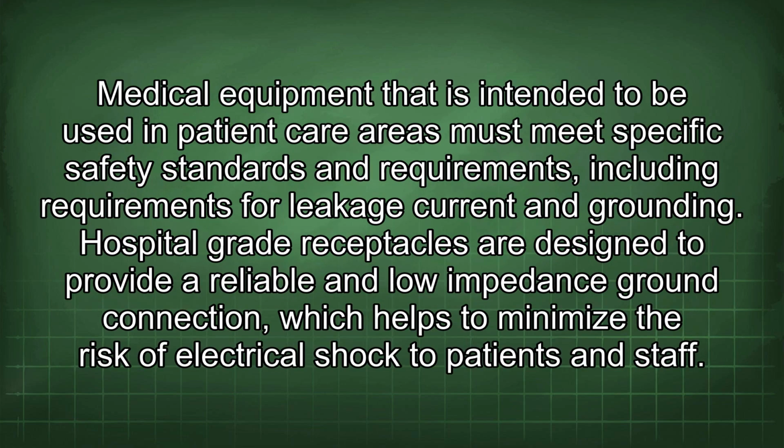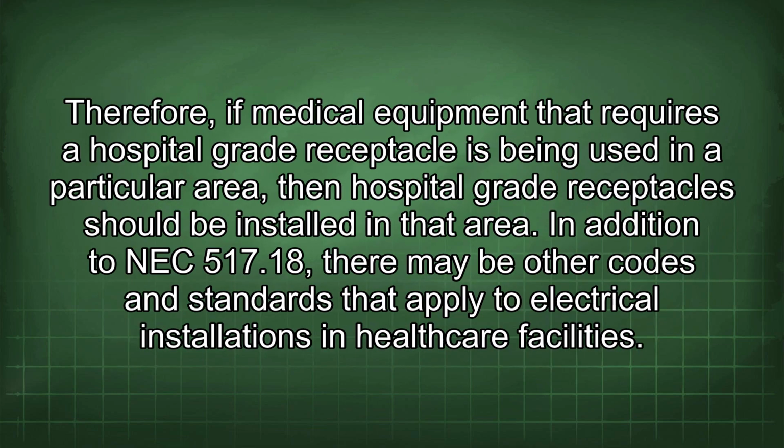Medical equipment that is intended to be used in patient care areas must meet specific safety standards and requirements, including requirements for leakage current and grounding. Hospital-grade receptacles are designed to provide a reliable and low-impedance ground connection, which helps to minimize the risk of electrical shock to patients and staff. Therefore, if medical equipment that requires a hospital-grade receptacle is being used in a particular area, then hospital-grade receptacles should be installed in that area.